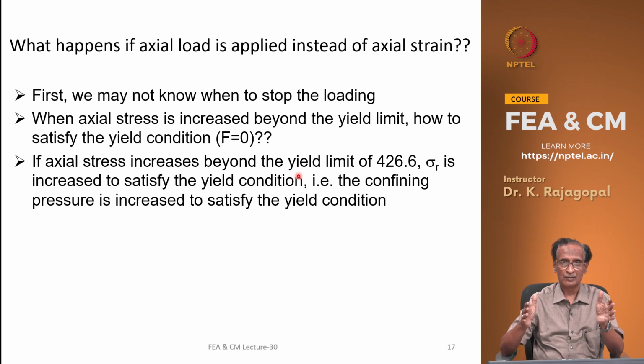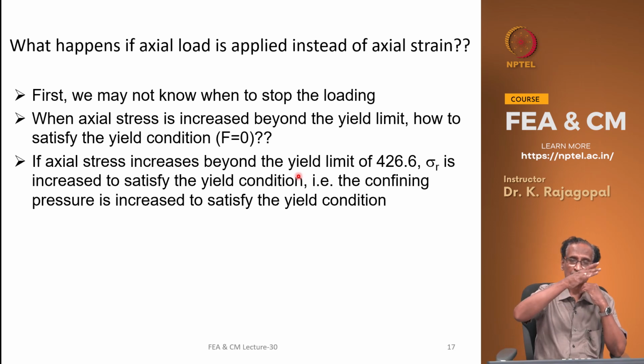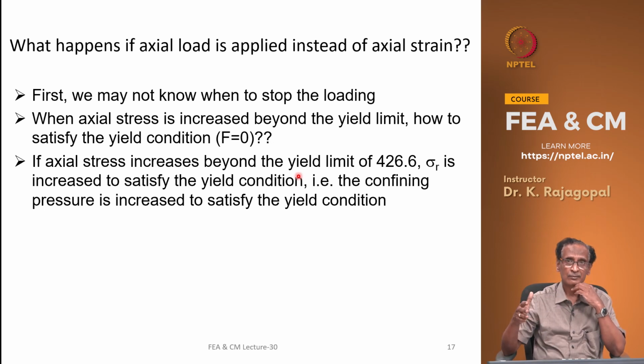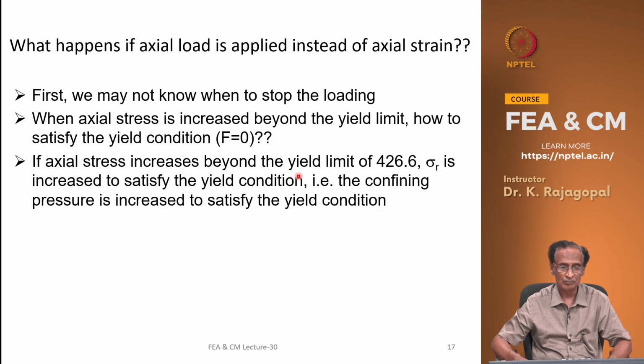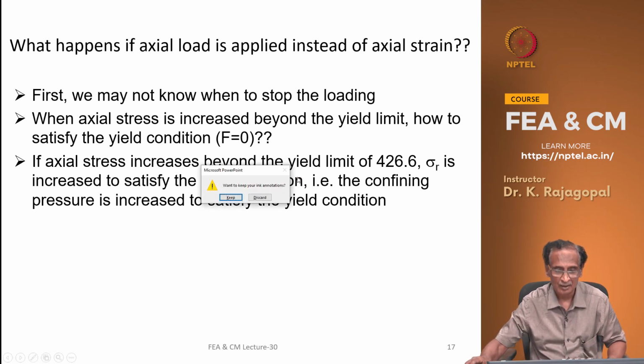Your lateral pressure will go on increasing, and then the strain that you get could be infinite strain, because suddenly you have failure, and if you are not careful enough, the entire program can reach a state where most of the diagonal terms on the stiffness matrix are 0, because you have reached the plastic yield limit, and in that case your strains will become very, very large, and your displacements also will become very, very large. Okay. So, let us look at this program.